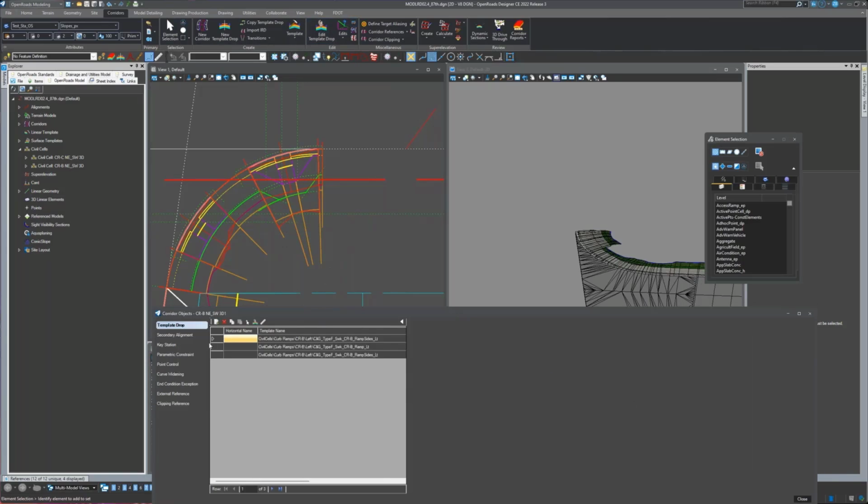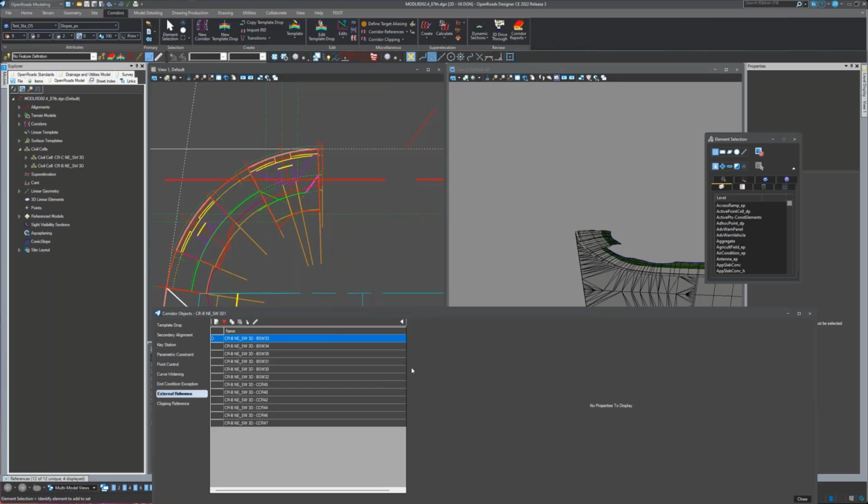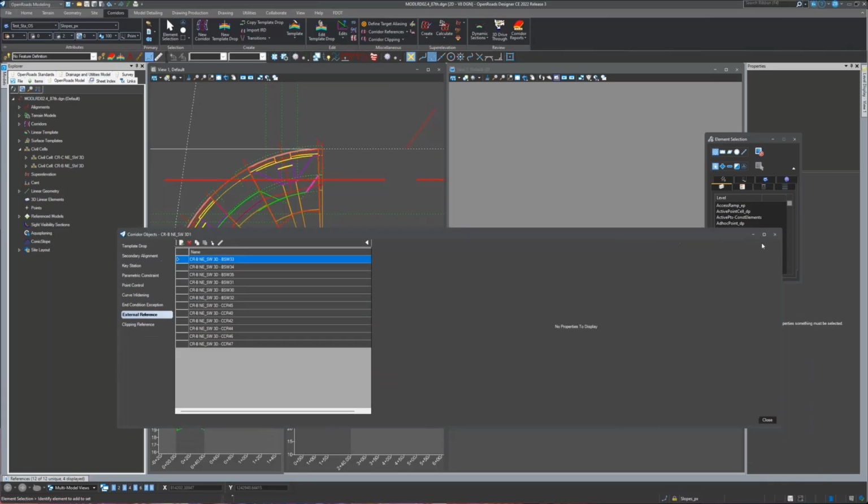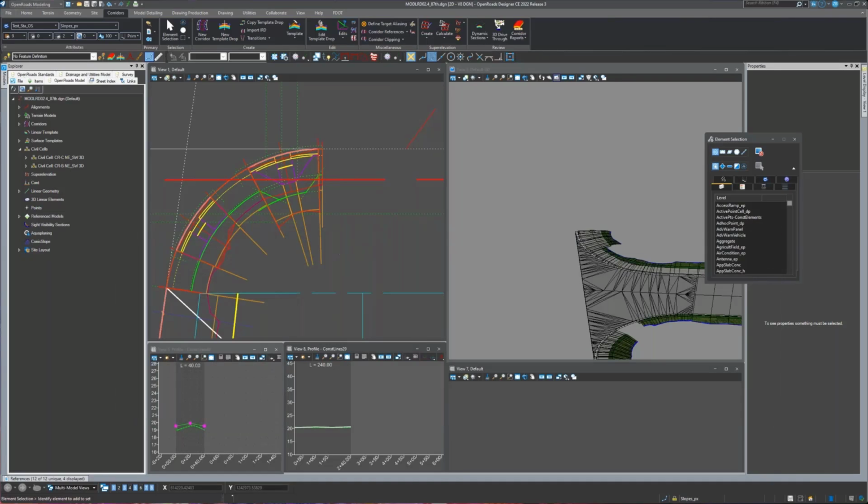I'm still confused as to why these external references don't work. But these numbers look different. Let's see, it looks like it appended the civil cell name to the original name. So I think that's how it's getting around the names changing, is they have the civil cell name before the actual name of the component as it is in the template library. So that would alleviate that issue.